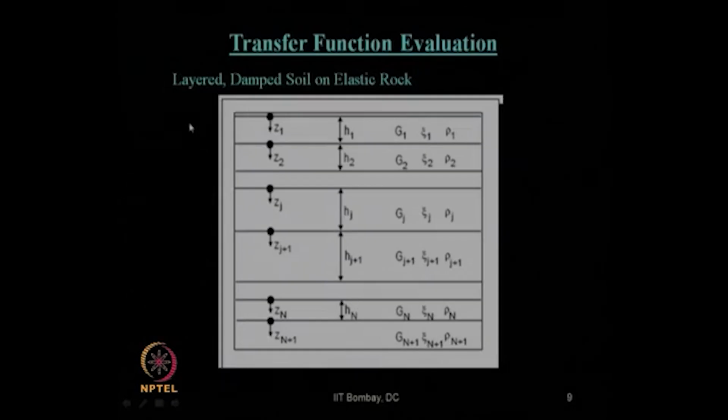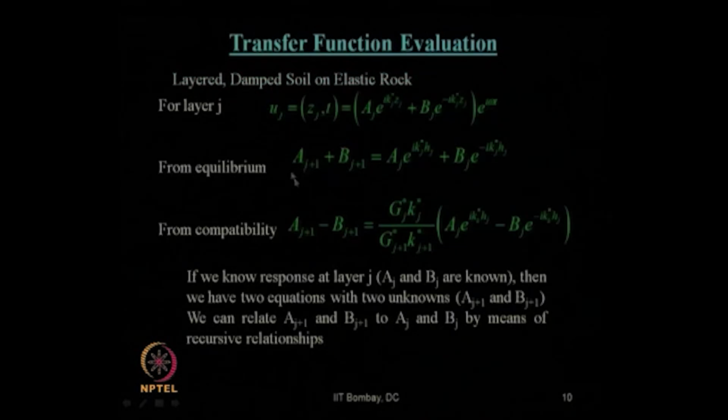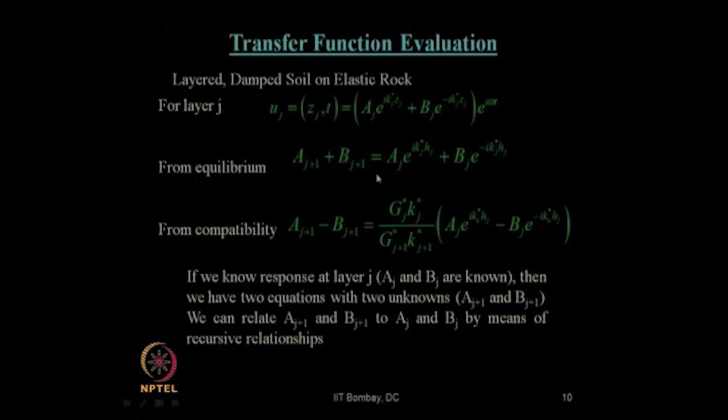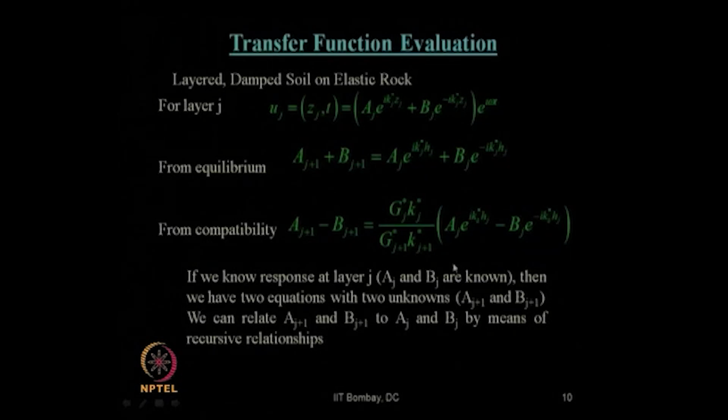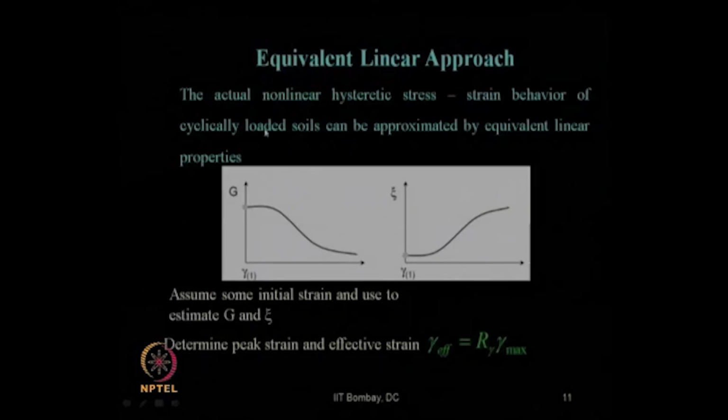Then we have talked about the most generalized case of layered damped soil on elastic rock. For that, we have seen that the displacement compatibility and the stress equilibrium between the layers have to be maintained, which by known boundary conditions will give us the values of various coefficients.